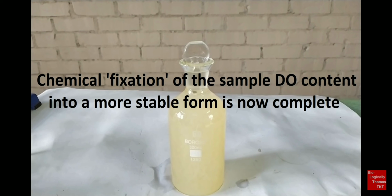If circumstances do not permit proceeding to the next step of testing the water sample, maybe because you are still in the field collecting other samples, or a lab setting is far from your location, etc., you may store the bottle in a cool, dark place for up to 8 hours and proceed to the next step once the situation permits. However, it is always advisable as far as possible that you proceed immediately to the next step without delay.